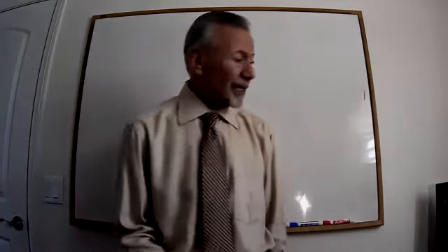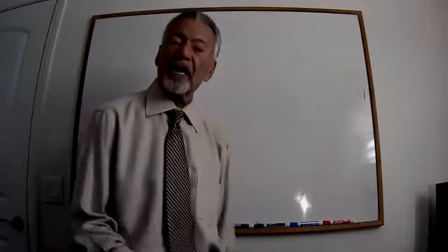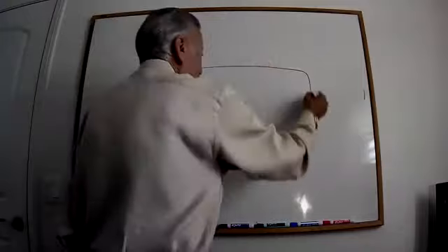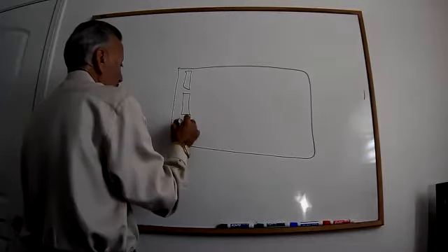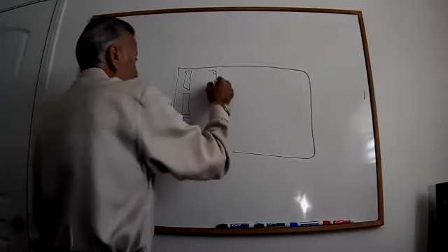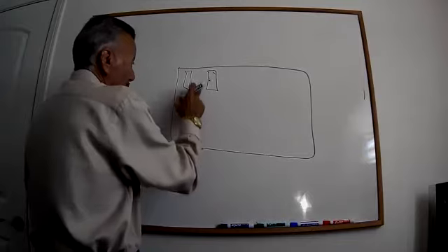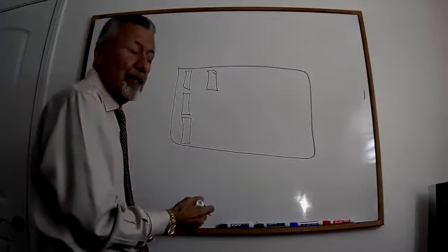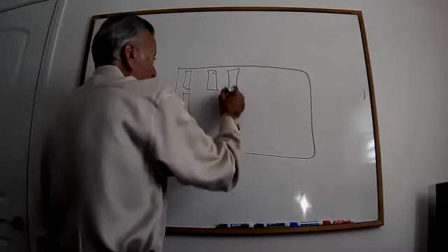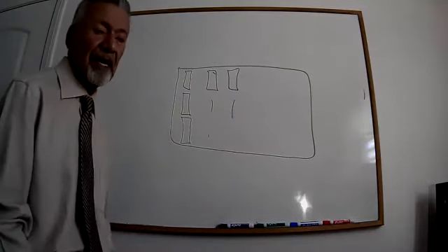So after the calculation, then the conceptual design layout. The conceptual design layout, I don't want any AutoCAD design with dimensions. Let's say you have a land and you want to put the solar. So you come up with the arrays of big panels, and you make sure you leave enough distance for maintenance and operation. Most importantly, you don't want the front panel to shade the panel behind it. So once you do the research, you find all of these things out. So this is how you're going to do it. That's your design layout. Simple as that.